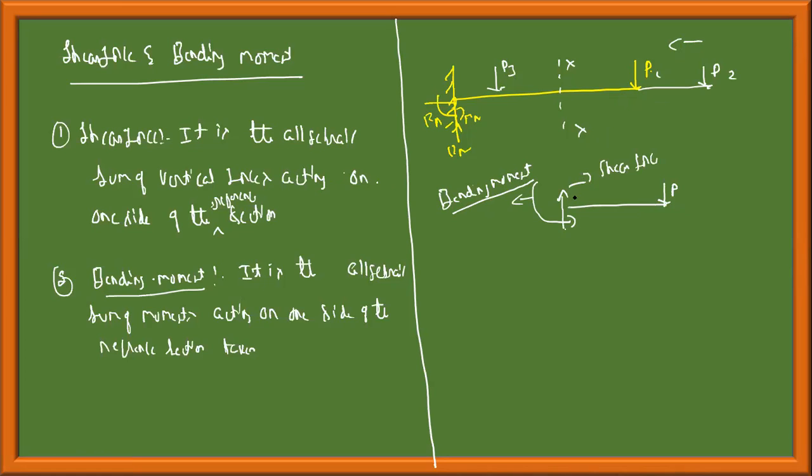So the algebraic sum of all these shear forces V from the end is called your shear force. For example, if there is one more section, X1, X2, which I have created here, what is the algebraic sum of vertical forces at this region? I will take the section here. The algebraic sum of shear forces in this region, that is P1, P2 plus P3. All these forces, if I take, give the shear force at this region.